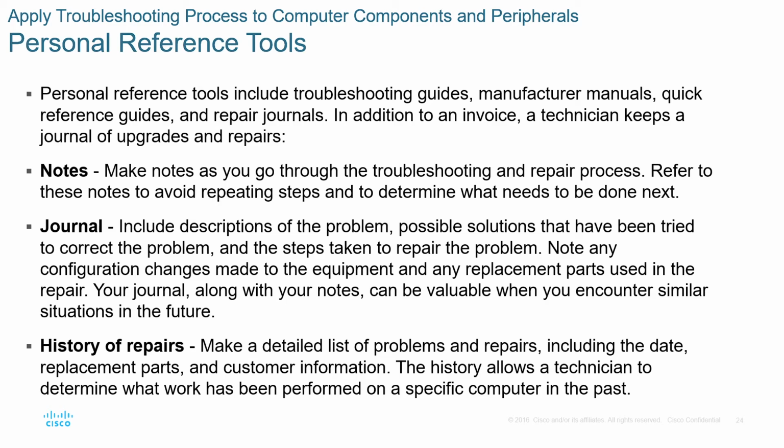Keep a history of repairs you have done. List the problems and repairs. Include the dates, include the replacement parts, and include customer information as well for warranty purposes and so forth.